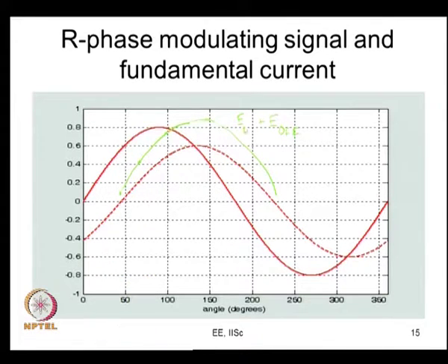During a turn on it is going to have a certain loss, which is called E on, and during the turn off it is going to have a certain loss, which you would call E off. So, this sum of E on plus E off is for one switching cycle. But that, let us say, varies like this.